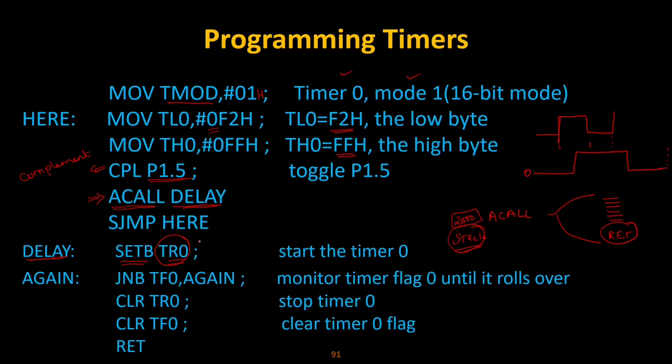So this is inside your TCON register. I should not push the values inside the TCON register. It is not needed because it is bit addressable, so I can use this instruction itself. Else, if you are more convenient using the TCON register, you can do that also. That is also fine, but this is convenient for me, so I am using this one. So this is being executed, and after that it is going to take this value.